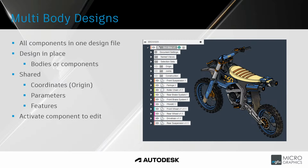All of these components have been designed in place within this assembly. So we have one single design file, and all of these components either started off as bodies, which were then converted to components, or they were components that were created empty and then activated and information then designed inside of that: extrusions, revolves, all the sorts of features that would build up a component.